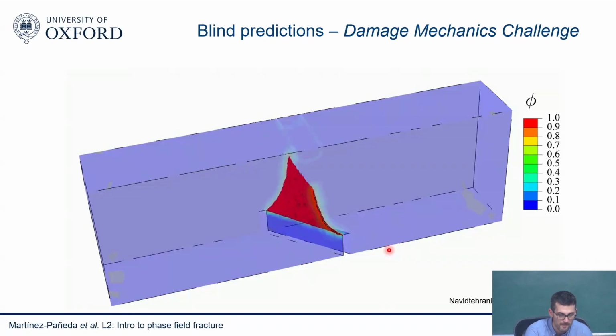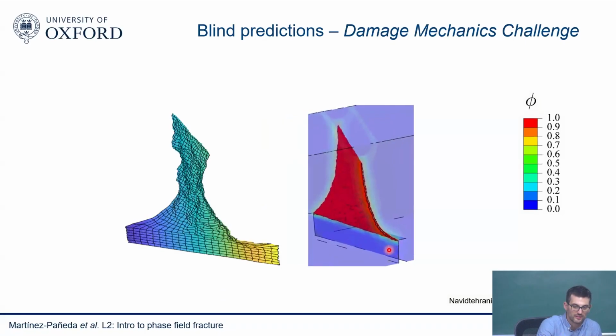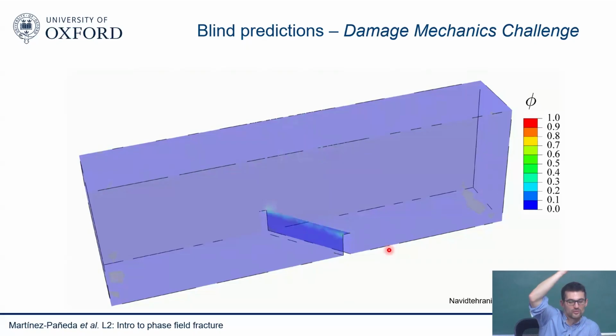Can we say initially it started as a mixed mode crack, and now it became a pure mode 1 crack? Yeah, cracks always like to go to mode 1 at the end of the day. So this is what we predicted, and initially it starts mixed mode because of the inclination of the crack. It's tilted, but then eventually becomes mode 1.